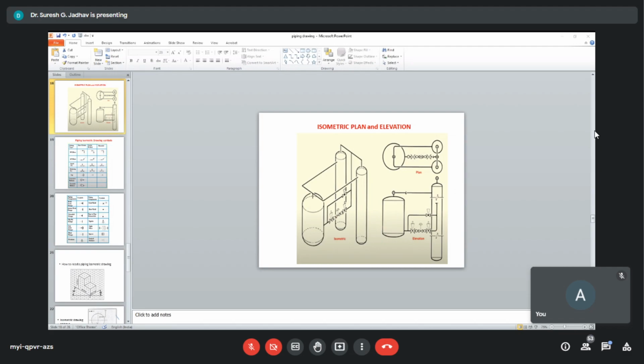Pipe size is always written at any connecting point of isometrics. Coordinate and elevation of pipe is written at connecting points of piping isometric drawings. Material description for pipe is described in the piping isometric drawing on the top right corner.